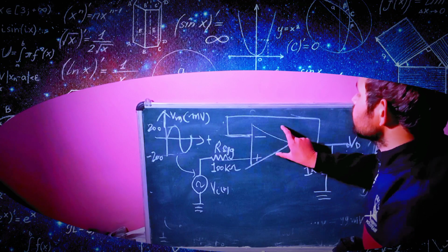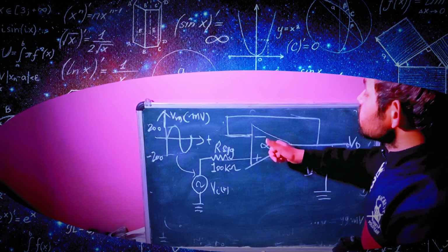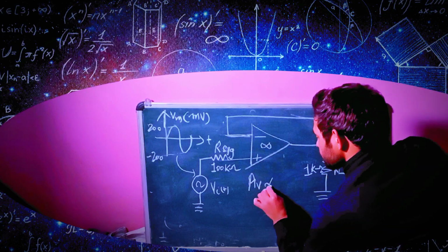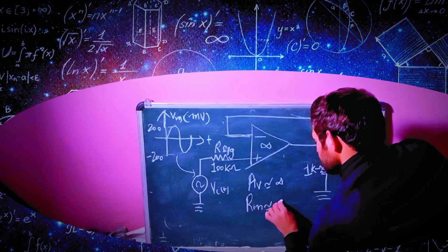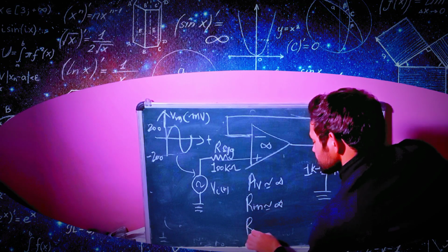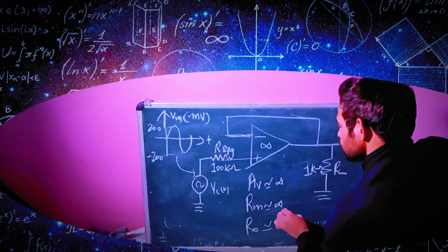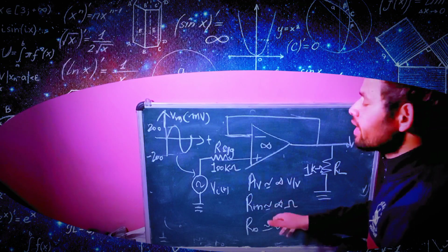Operational amplifier. I am assuming this operational amplifier as an ideal operational amplifier whose voltage gain is approximately infinity, whose input resistance is also approximately infinite, and whose output resistance is approximately equal to 0 ohm. Yes, so this is the ideal operational amplifier characteristic.